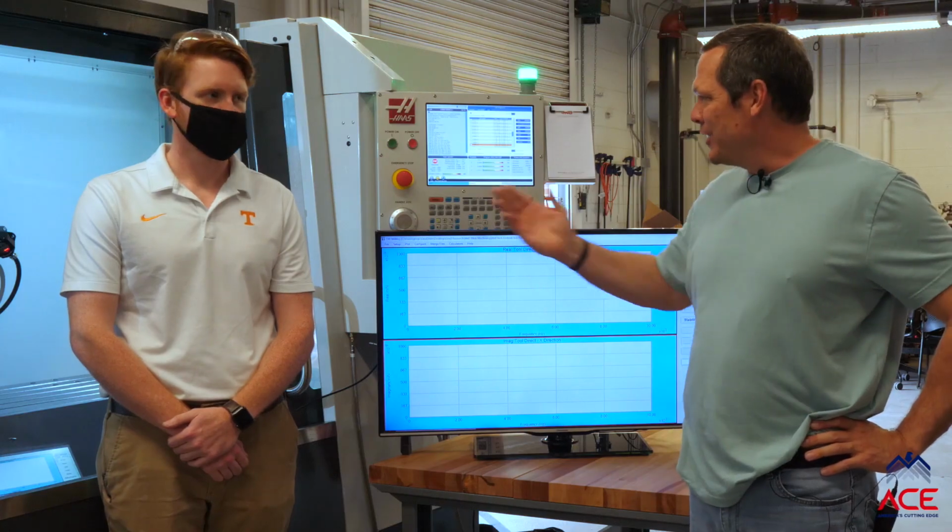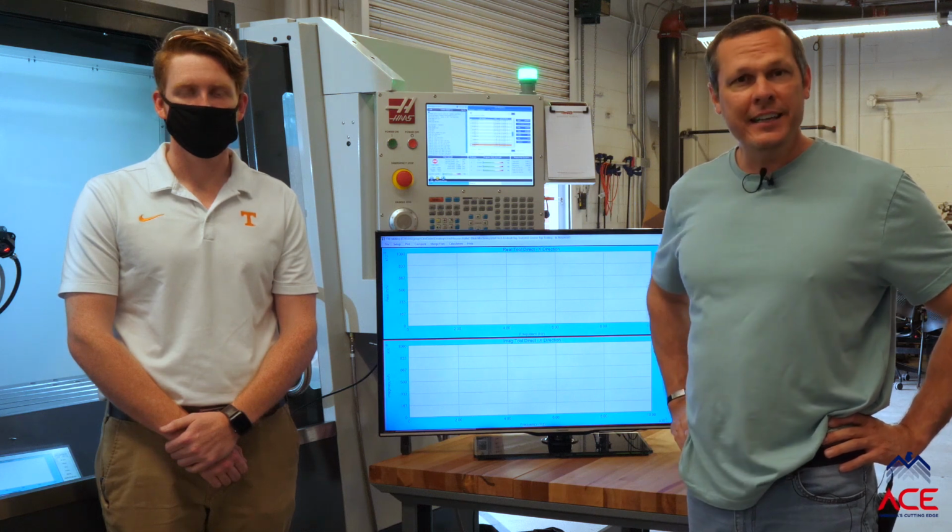Today we're going to do a chatter demonstration that will be composed of 3 parts. The first thing we'll do is measure the tool tip dynamics using tap testing. My colleague here, Greg Corson, will be doing the tap testing for us. Once we've identified the tool tip dynamics, we'll predict a stability map. Given that stability map, we'll select machining conditions. And we'll do 2 machining conditions. The first will be for chatter, and the second will be for stable machining conditions, and we'll hear and see